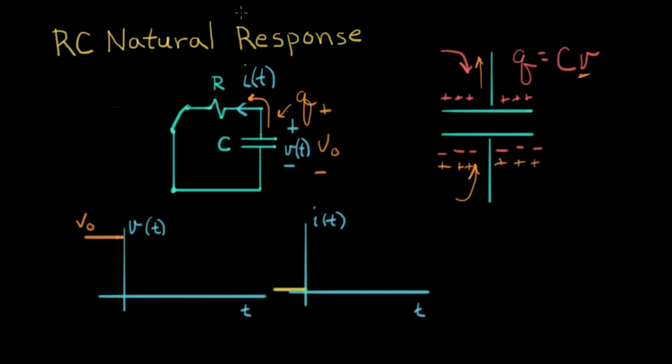So we can draw that. After all this charge rushes out of here, goes through the resistor, and ends up on the backside of the capacitor, neutralizing the charge in the circuit, the voltage in the circuit is going to be 0. We draw the long time from now out here. It's going to sketch in as something like that. It's going to be low. Likewise, the current is going to end up at 0 when we're finished here. And that's what happens with every natural response: the energy in the circuit is allowed to die to 0.